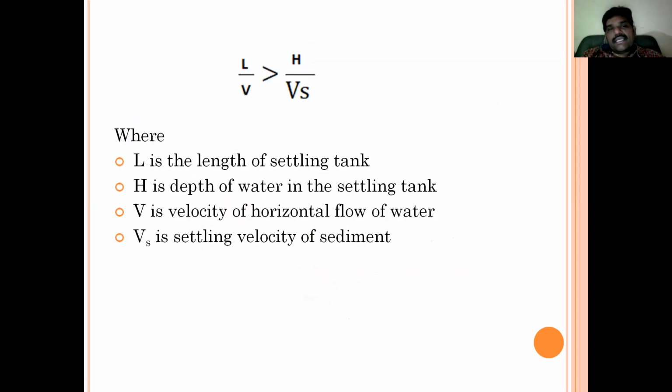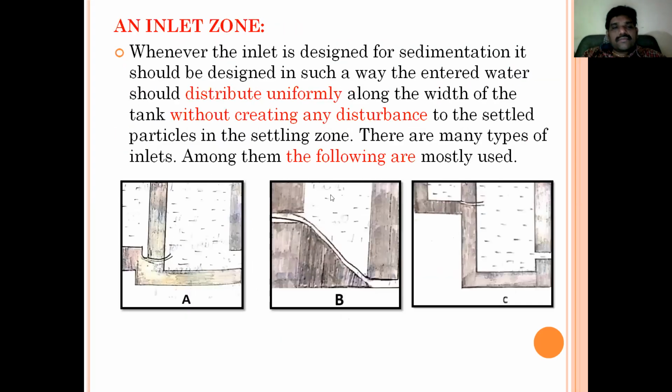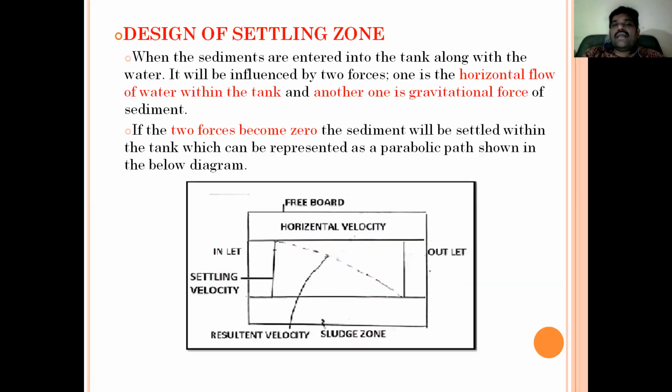In the inlet zone, the water enters. What are the fundamental points we remember? The settling particles should not create any disturbance to the settled particles, and the water should distribute uniformly around the tank. And these two, along with the design of the settling zone.